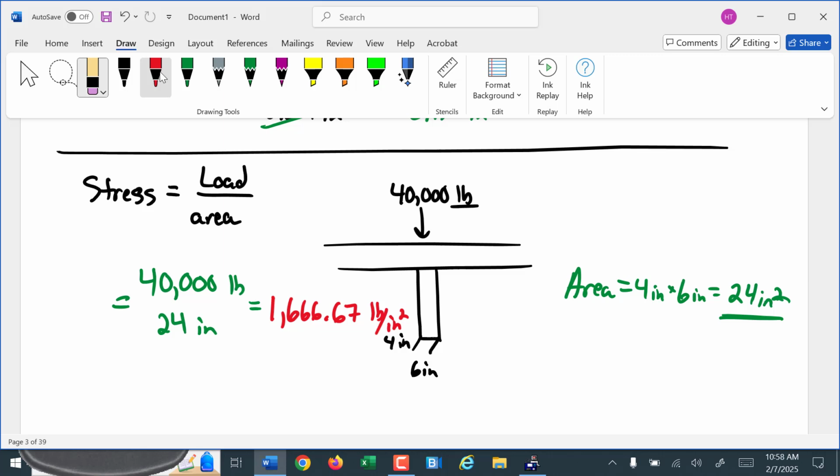Typical load for wood, by the way, non-graded wood is 1150 to 1200, but you can have 1600, 2100, or 2400 PSI grades of lumber. So if you get this calculation, it's telling you that you have to grade up to a higher grade of lumber. You can't just use standard number 2s.